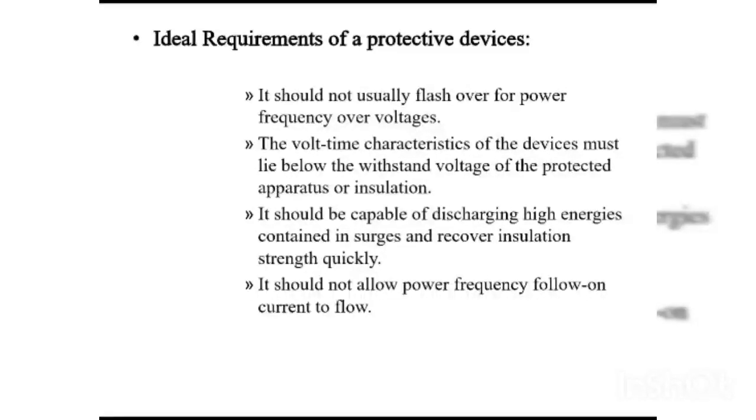Now let's discuss the ideal requirements of a protective device. It should not cause flashover on power frequency over voltages. The voltage-time characteristic of the device must lie below the withstand voltage of the protected apparatus or insulation. It should be capable of discharging the high energies contained in surges and recover insulation strength quickly. It should not allow power frequency follow-on current to flow.